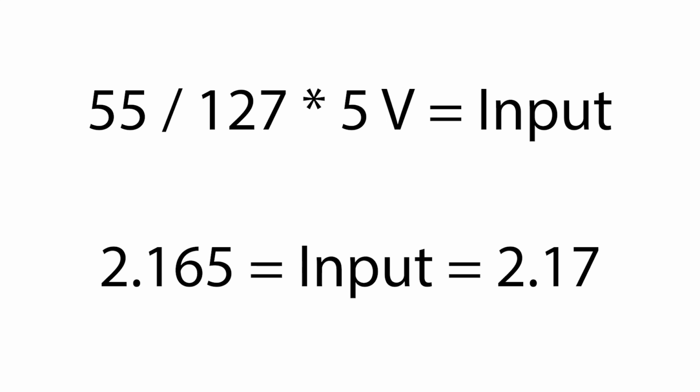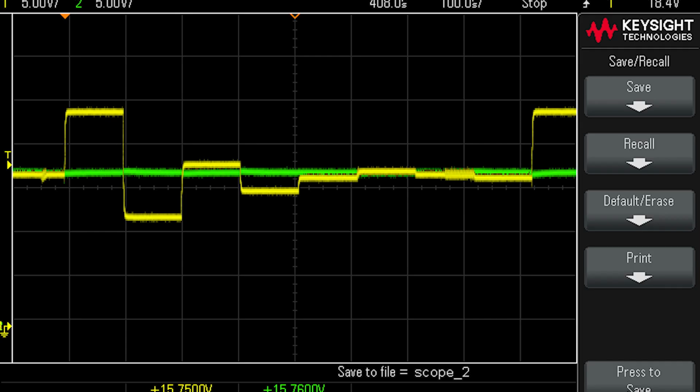It's pretty hard to show what's going on in this circuit by just using LEDs and DMMs, so a better tool to do this is looking at the oscilloscope. Here's an image from the oscilloscope looking at the output of the DAC. As you remember, the DAC is used to essentially guess what the input voltage is. You can see as the cycle of the SAR continues, the guess from the DAC is more and more accurate.